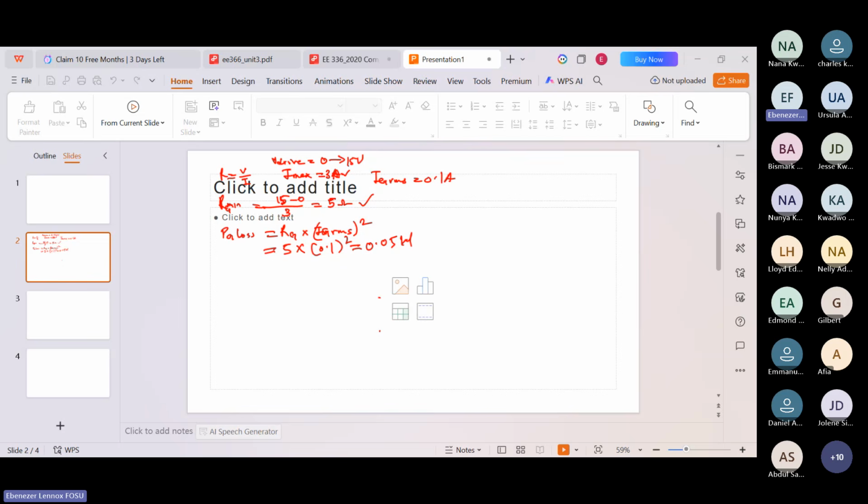You remember there is a formula like this, which is 1 minus e exponent minus t over RC for a capacitor. So this is the charging voltage, and the discharging voltage is given by V naught e exponent minus t over RC. So this is the formula that we are going to use. Since it is charging the gate capacitance, then we have to use the first one.